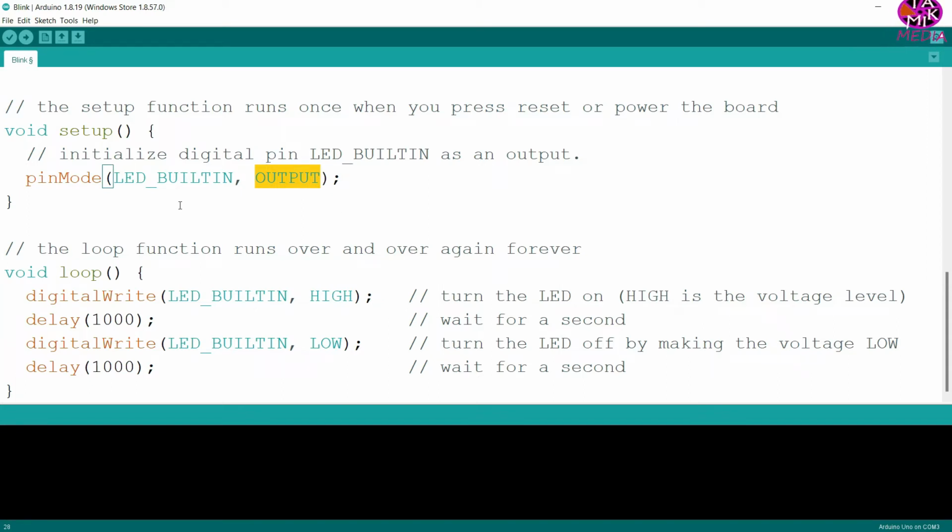One thing you need to know is that an Arduino sketch is case sensitive. Let's write a small l here. You see, it is no longer an instruction now. Use a semicolon after each line. So we have declared pin 13 as an output pin. It will run just once.